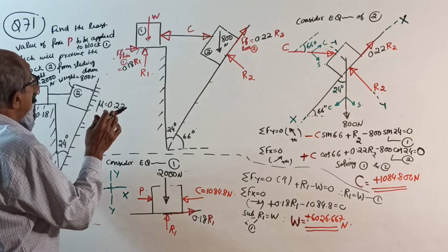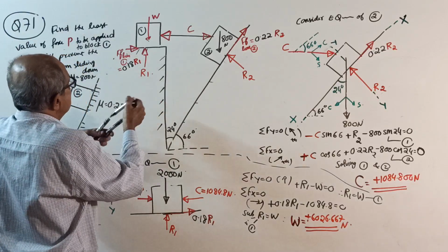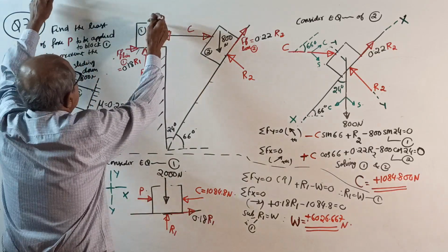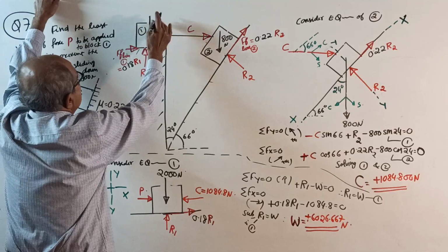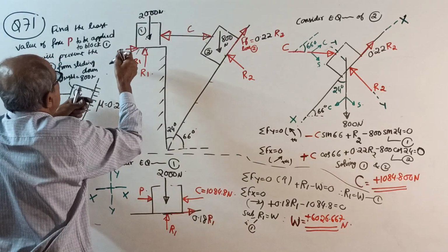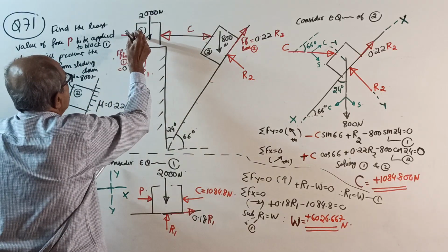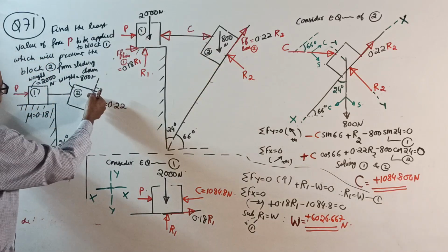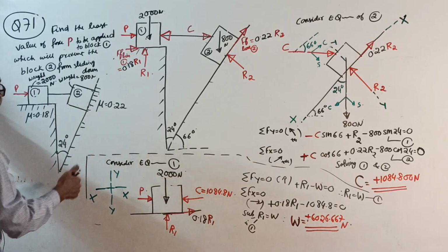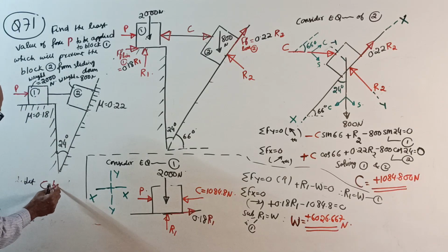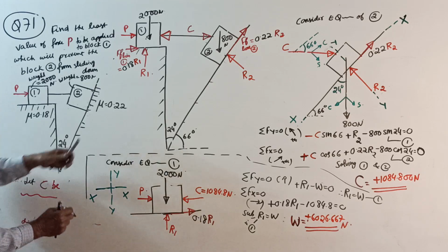Okay, start. See now, the unknown is here. Not weight. When you draw the free body diagram, this weight is given to you. How much? 2000 Newton, given in the question. Now there is an unknown here, P. Everything is same as last time. See here, this one is same, this one is same. You also write one more thing: CB, compression force in the connecting member.